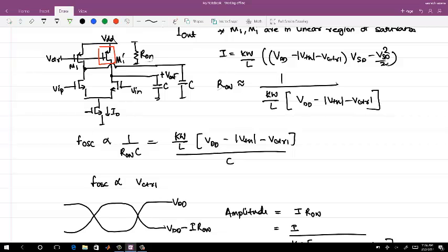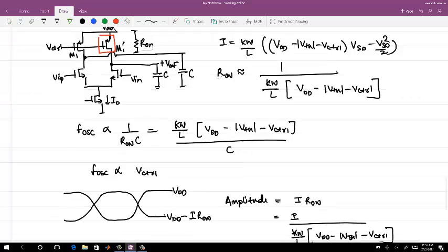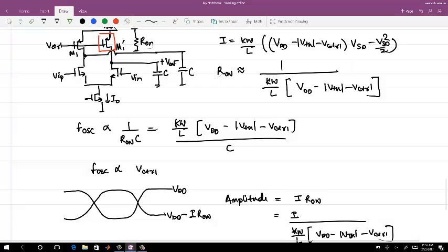You can't comment on that. You are having two current sources, top and bottom, and nothing controlling in between, right? So it can switch to one side depending on the current. Means in a practical sense, either this node is going to be VDD if the current is so small, or if the current is so large, then it will basically pull down to zero, and even the current source will get crushed. So maintaining this in a linear region in the presence of a swing is important.